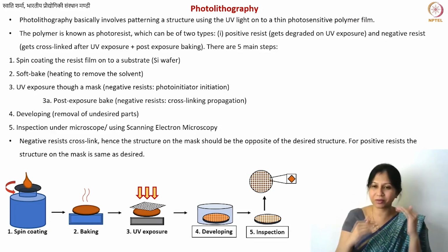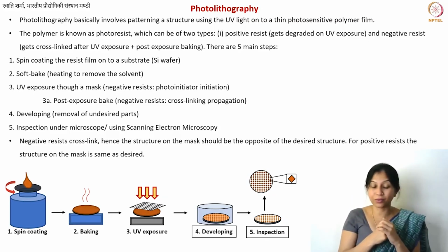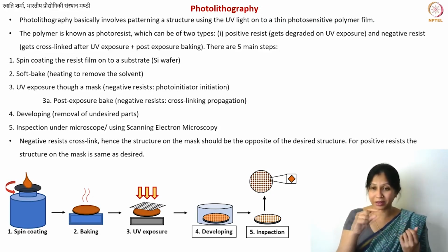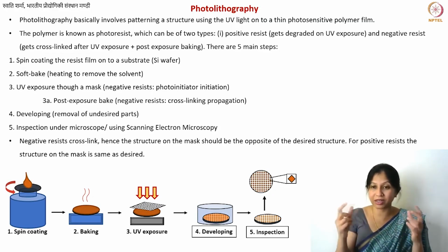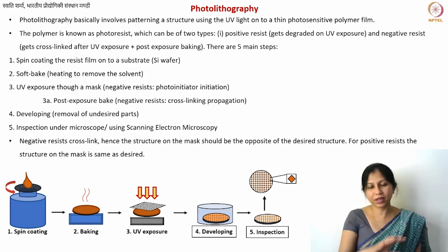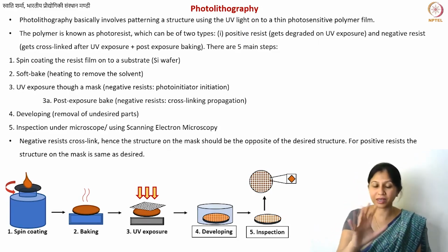Your mask is in the proximity of your wafer, but not completely touching. You would do that, let's say, in the case of a polymer where you cannot avoid a certain liquid part, or the polymer does not become hard before the exposure, so you don't want to attach the mask to it. So there are many other things, many other techniques, in the details of photolithography. But at the end, what you're getting is these kinds of structures on top of your silicon wafer.